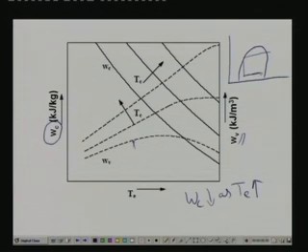Let us say that this is your original pH diagram, and this is your work of compression. Now if I am increasing this evaporator temperature, then you can see that this will get reduced. That you can verify even from the earlier diagram also. So it has quite a significant effect. As your evaporator temperature increases, work of compression reduces, and the work of compression reduces as your TC reduces.